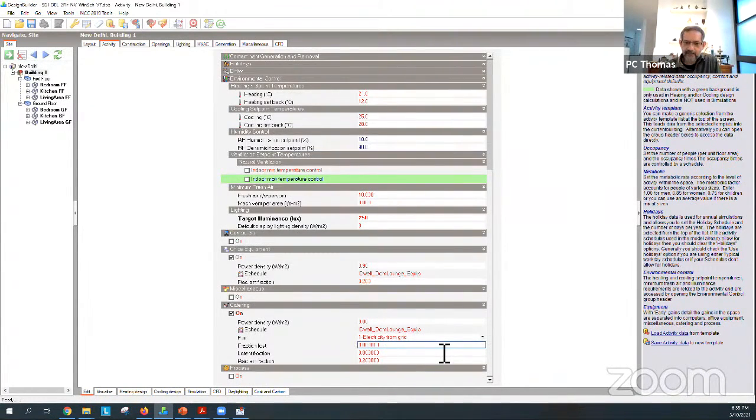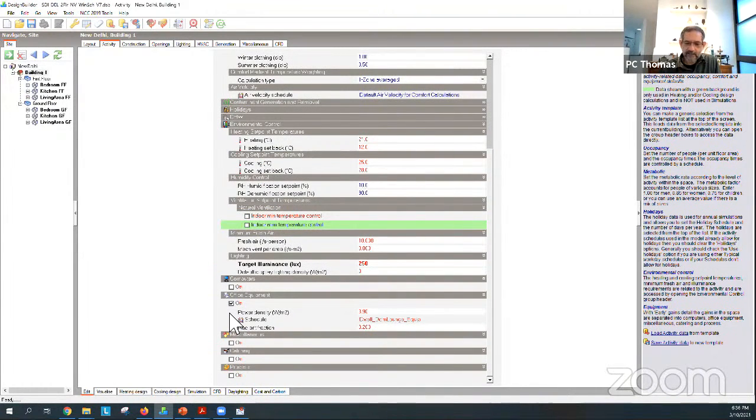That's increasing the temperature and the humidity within the space. If you have to condition that space, you need to consider that. If you're in a restaurant, you're being served hot meals, and there's a lot of latent load coming from that. So you need to then switch on a catering load. But otherwise, typically, they're all sensible loads, okay?